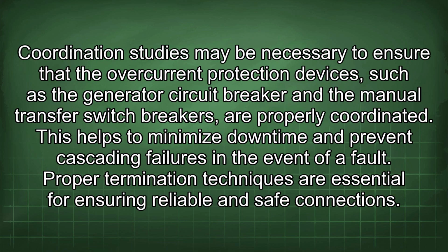Coordination studies may be necessary to ensure that the overcurrent protection devices, such as the generator circuit breaker and the manual transfer switch breakers, are properly coordinated. This helps to minimize downtime and prevent cascading failures in the event of a fault.